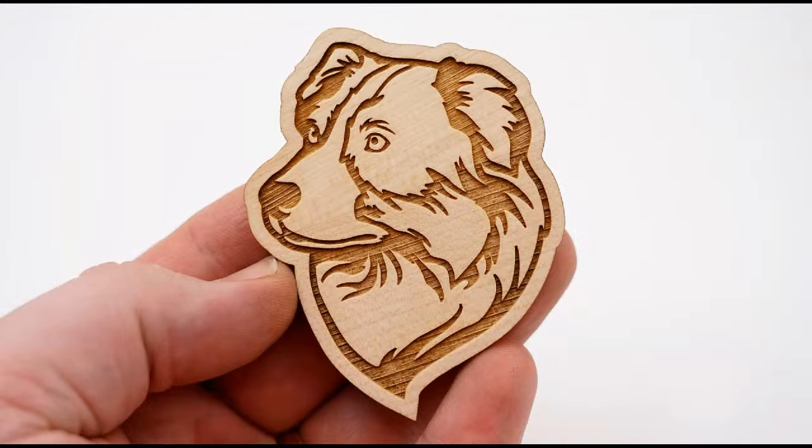So the boundary tool quickly creates the outline, and then the contour effect makes a perfect offset of your dimension, and then allows me to quickly engrave and cut that out. And so within seconds, I'm able to design my graphic, create an offset of it, and then send it to the laser, cut and engrave it with a contour offset, creating a finished graphic like this.